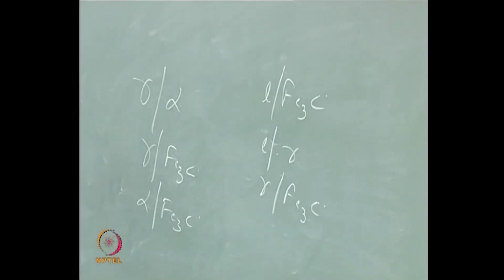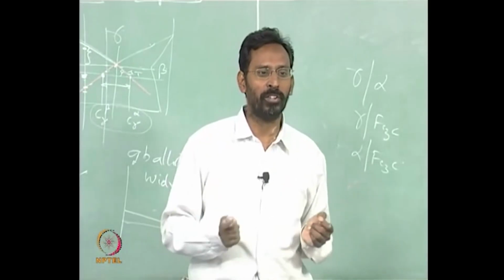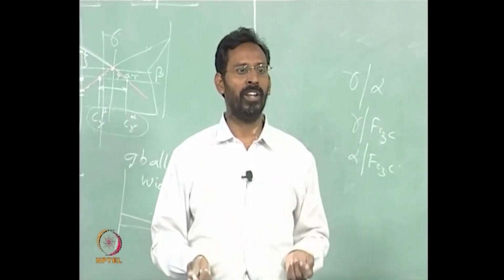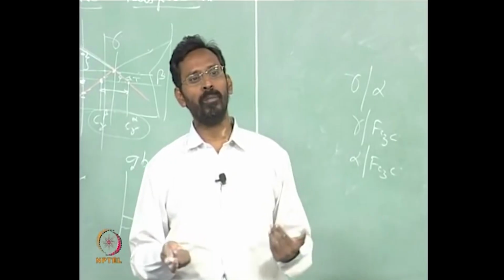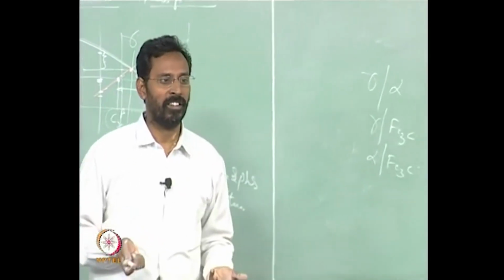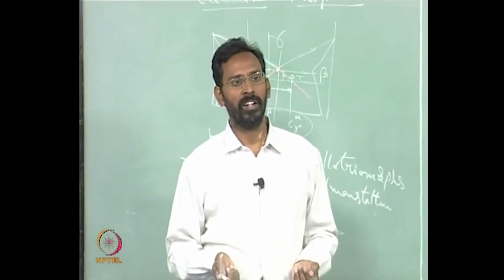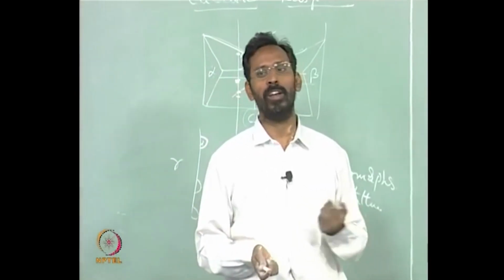It looks at which is the lower interfacial energy, and whichever is lower would happen. One more thing is, once it nucleates, whether it grows as chunky or not depends on the growth rates. That is what I have just now said. Some of them would grow as needles. There are a number of cases in eutectics where you have needle-like or rod-like microstructures. Aluminum silicon is an example. There are also examples of lamellar eutectics, isn't it? Aluminum copper is an example where you have lamellar eutectics.